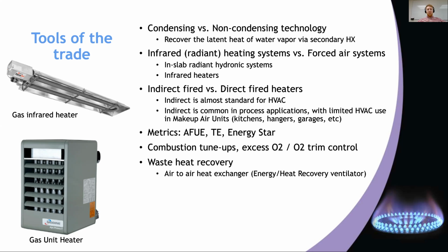And they don't follow the same efficiency as a forced air or a hydronic system because they're really not heating anything. They deliver heat directly to the recipient. They don't heat an intermediary layer. So they can be very useful in terms of delivering it directly to areas where people are working instead of heating a large volume of air and delivering that to the occupants.